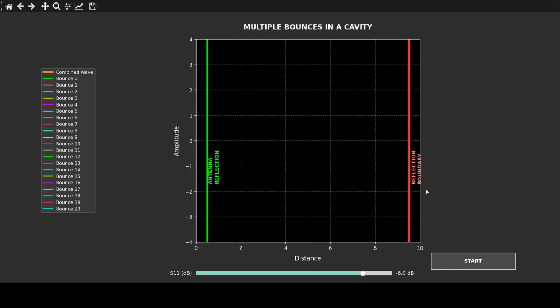One of the things that is making RF design different than low frequency design is because now we are operating at higher frequencies. We want to now take into account the wave behavior of our voltage or our currents. So when they are being transmitted along a transmission line, because of their wave behavior, their voltage oscillates. So let me show you here what I have.